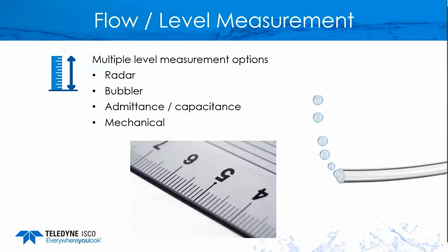Other flow measurement devices could be radar. Radar operates in a similar fashion to the ultrasonic sensor. It transmits a radar signal, and it's a function of time to get that return signal. They do have some advantages on radar systems. The range: a typical ultrasonic range is usually 0 to 10 feet, whereas a radar, depending on the sensor, could go up to 30 feet, 100 feet.